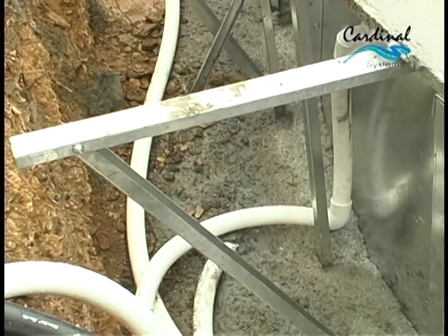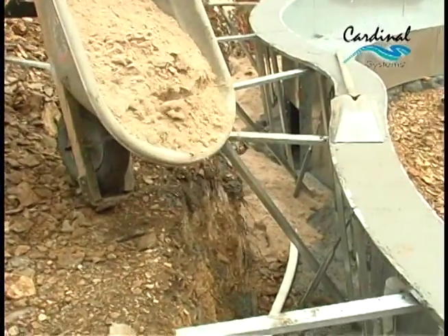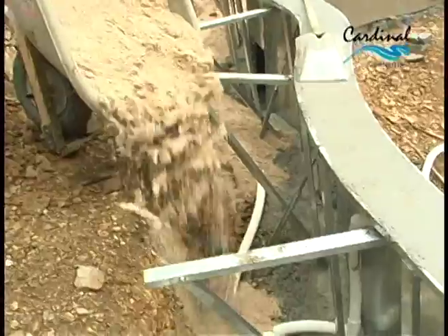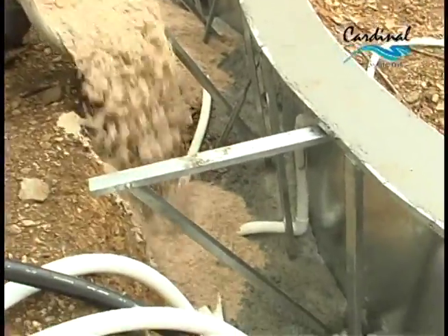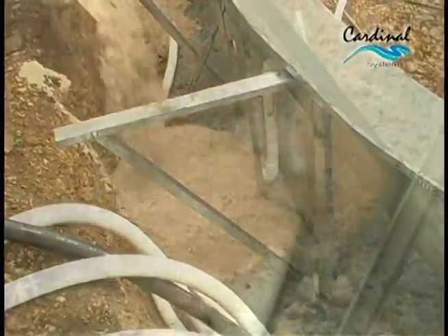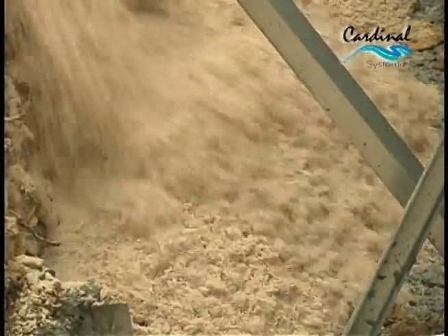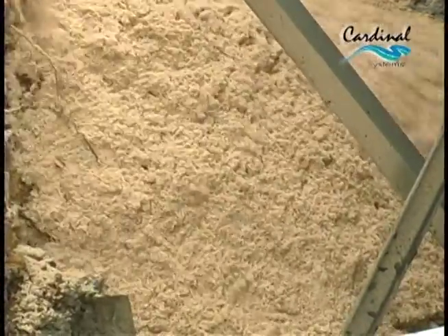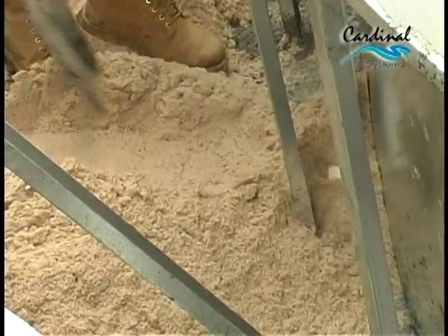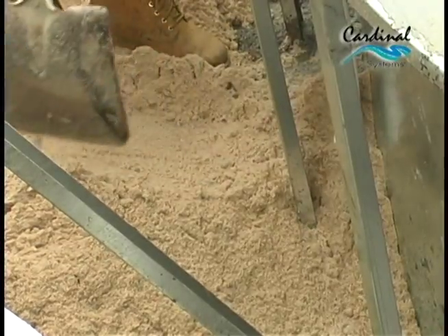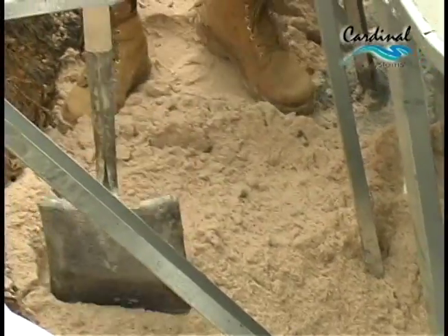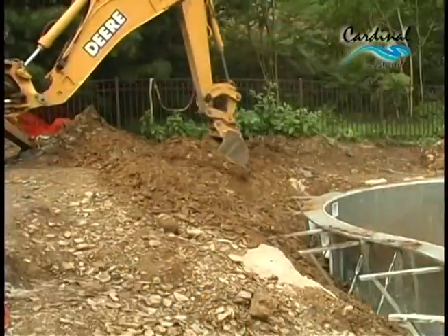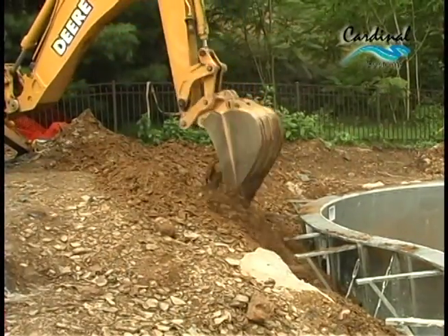With all the plumbing complete, it's recommended you cover all plumbing with a liberal layer of sand before backfilling. Often, backfill material has large rocks, sharp shale rock, and other such debris which could be detrimental to the integrity of the plumbing. This layer of sand will provide protection. Then, backfill on top of the layer of sand.